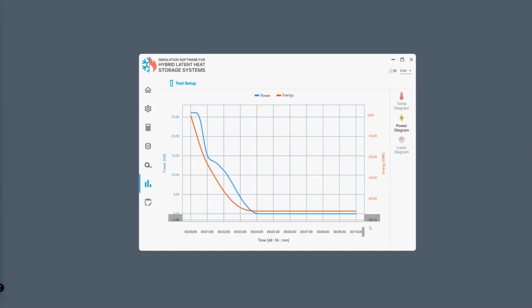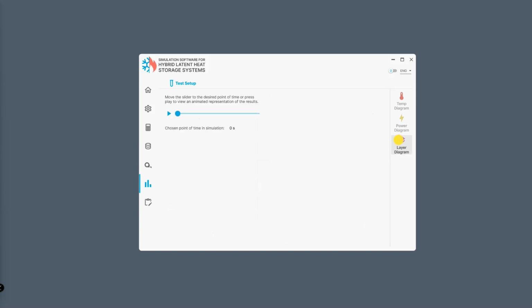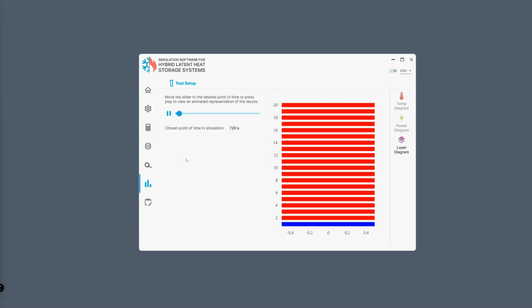Now this is a simulation which shows the temperature distribution inside the tank and its behavior. We have 20 layers which deliver hot water in the upper layer, that is the 20th layer. If you see here, cold water is going into the system from the bottom, and the system delivers high temperature until 4 hours and then runs empty.